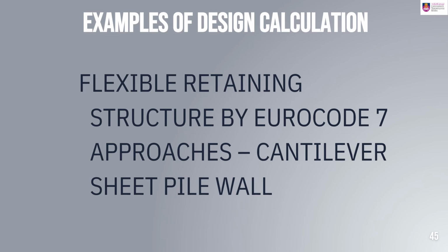In the limit state design method to establish the required design depth, the depth D is obtained by balancing the disturbing and restoring moments about C together with the horizontal forces established using the pressure distribution. So, in Eurocode 7, the GEO limit state is applied to assess the rotational stability using this theoretical pressure distribution. The method generates two equations containing the unknowns d and d naught, which are solved by repeated iteration until the correct values are obtained.